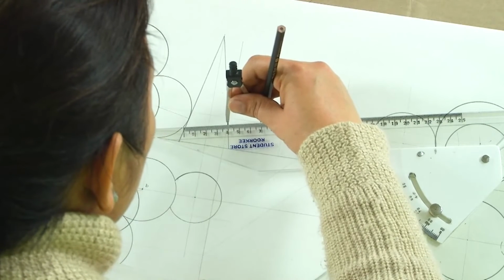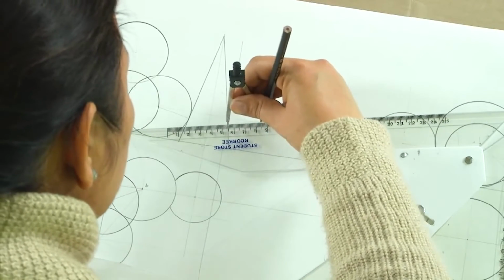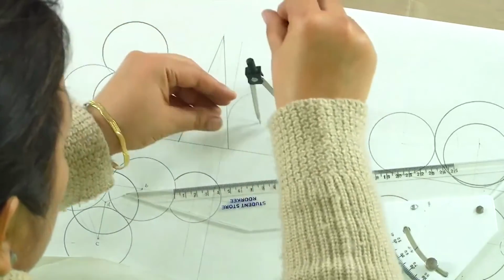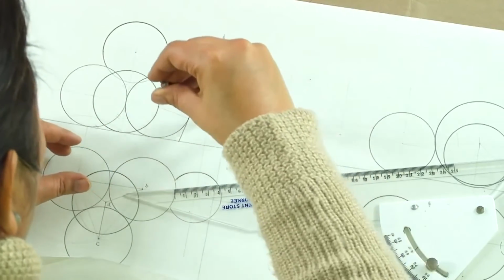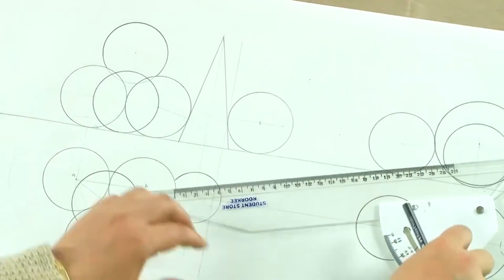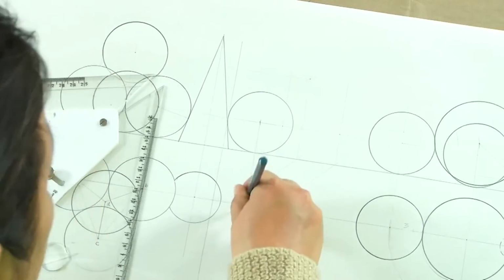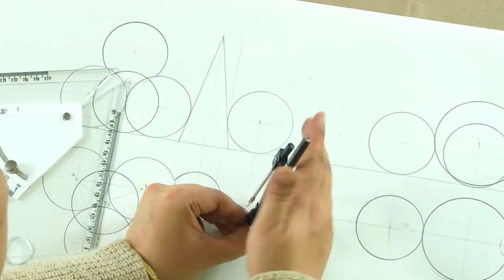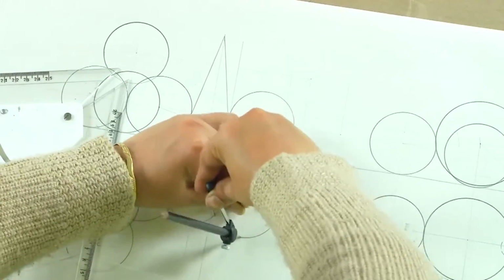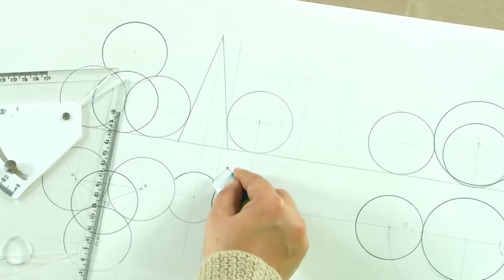So, we will mark the center of the sphere, and we will draw the sphere which will be touching the surface of the cone, which will be touching the ground. And this is what the other sphere would be. We will again locate the center of this and draw it in the plan. What you see in the plan is that this sphere again overlaps the cone, so we will actually not see this part of the cone again.